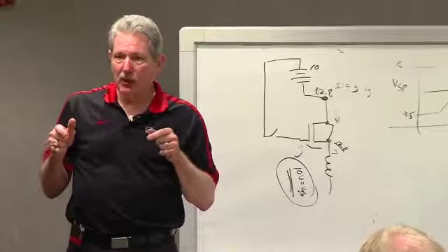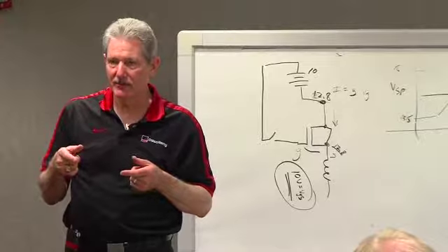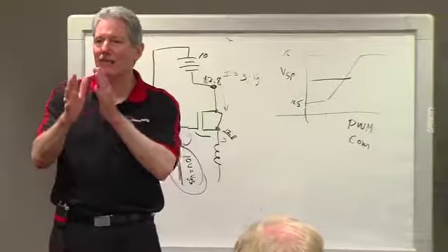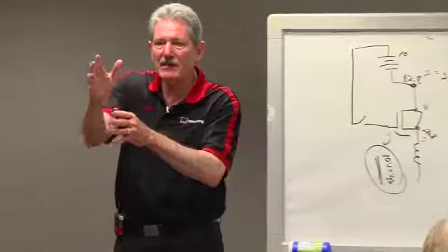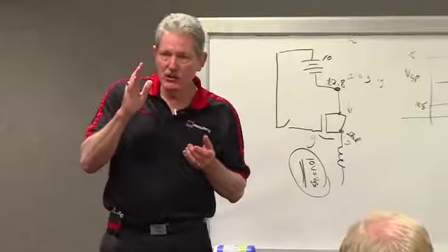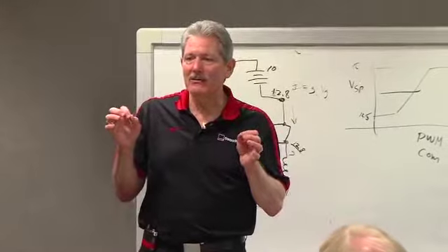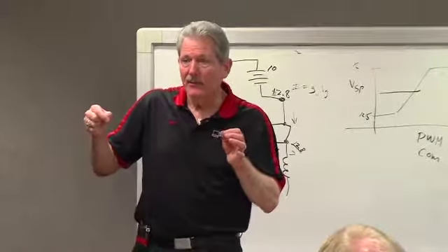Patrick brought up a good point yesterday. Why would we do that? One, a good reason is now I don't have to have all those wires. I can convey 6 or 7 or 8 pieces of information with one wire. The instructions on this LIN travel at 19,200 bits per second.